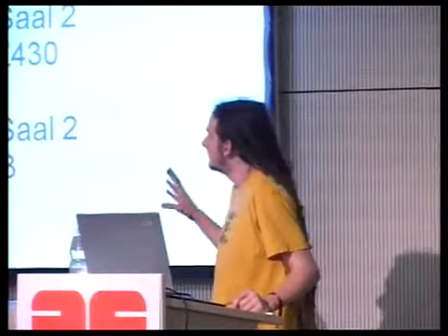So I printed out the disassembly of the code, and then for a couple of days I went through and annotated the different pieces of it. The lecture that I'll be giving on the 29th in Sal 2 on repurposing the EZ430 describes the tools that I used for this. I've got a Perl script called MSP430 static that lets me identify every function that contains access or code that writes to a particular I/O port. In the BSL code there's a read byte function and a write byte function. And then there's a tare function that reads the 0x80 and bases a timing guess upon that. The program is only 500 words long, 1 kilobyte. That's a hard limit by the architecture. So it's feasible for a human being to go through and learn it all.